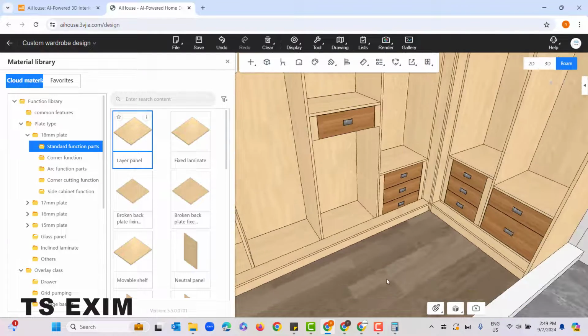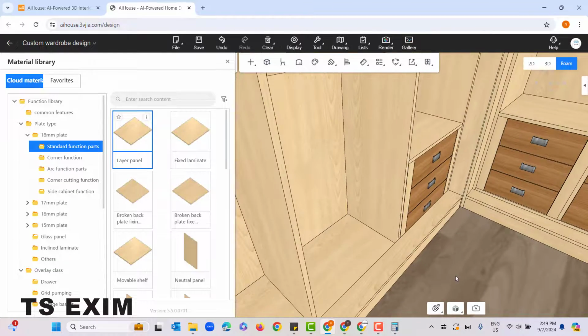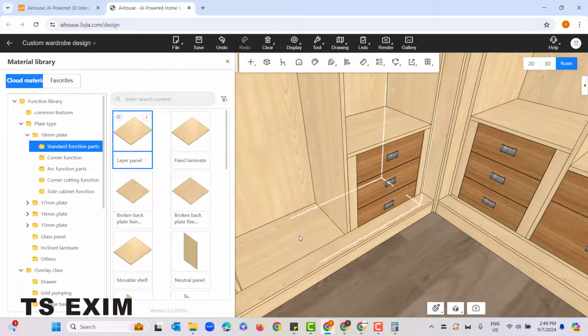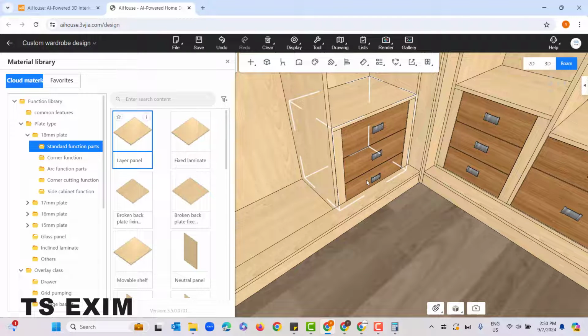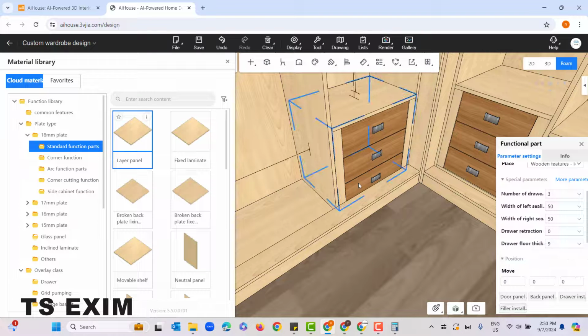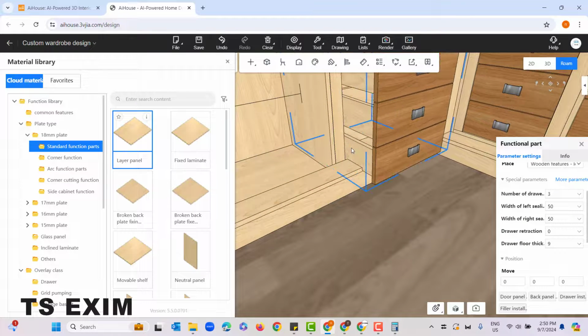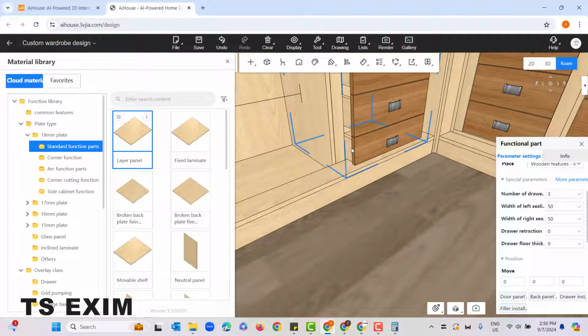And one more thing, if you drag a drawer to the left side, you can double check the bottom drawer, because remember our bottom panel is below the skirting height. You can open the drawer: select the drawer first, then press O. You can see my bottom drawer is overlapping with the feet. You notice it? It's overlapping with the skirting.